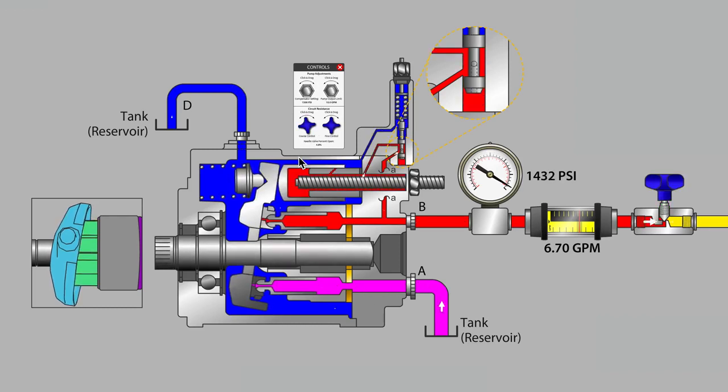Suffice it to say that the pump has begun to compensate for the fact that we're coming close to the maximum system pressure. Our maximum system pressure was set at 1500 psi, and here we are above 1400. We're very close to the top pressure. And so, a pump that has the ability to be variable displacement is now showing that it has changed the angle of the swash plate. If you were observing at the beginning of the video, you saw that we had 10 gallons per minute of flow present, and now we are below 7.